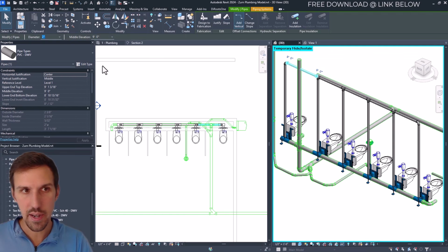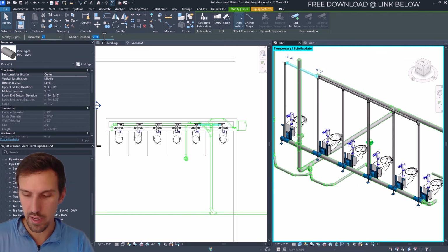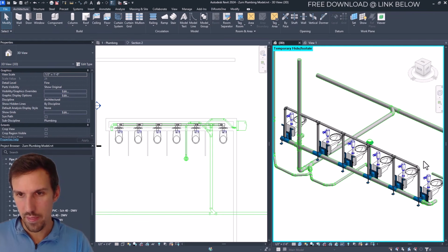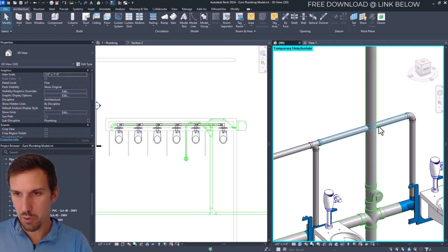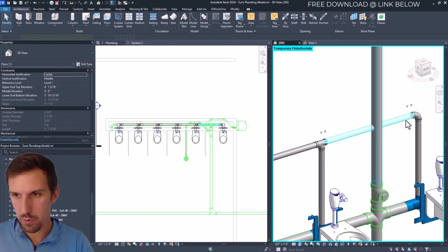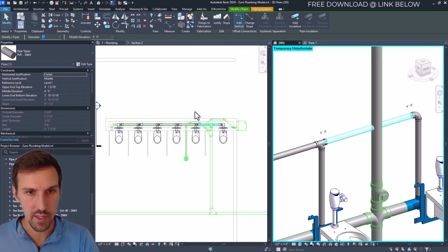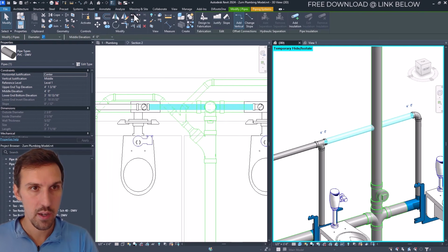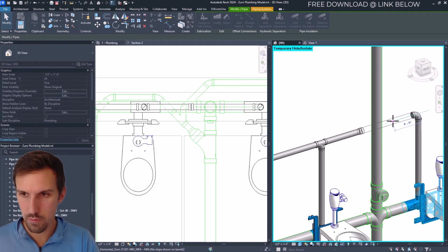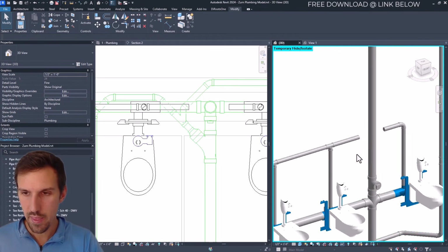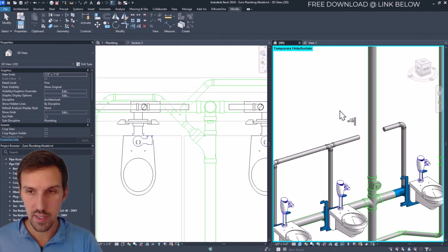Now I might not need it at 9 feet, so maybe I'm going to put it at like 4 feet. And that looks really nice. Okay. And so then I'm going to go ahead and make sure it's teeing into this correctly. So I'm going to remove this piece right here. Maybe I'll split it. So I'm going to go into my view here, and we're going to use the split element button, and we're just going to split that, and we're going to drag this over and delete that. And then I'm just going to use my trim extend single element to trim that together.